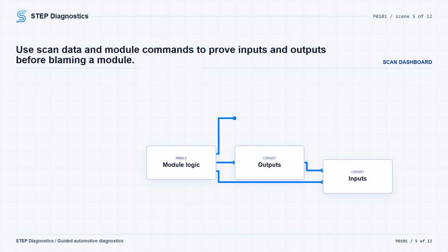Use the scan tool to read PID input values, output states, and diagnostic states. Monitor the data in data logger so you can catch what the module is seeing without unnecessary disassembly. Before blaming a module, understand normal system operation. Make sure programmable parameters are set correctly. Resolve codes in the proper diagnostic order.